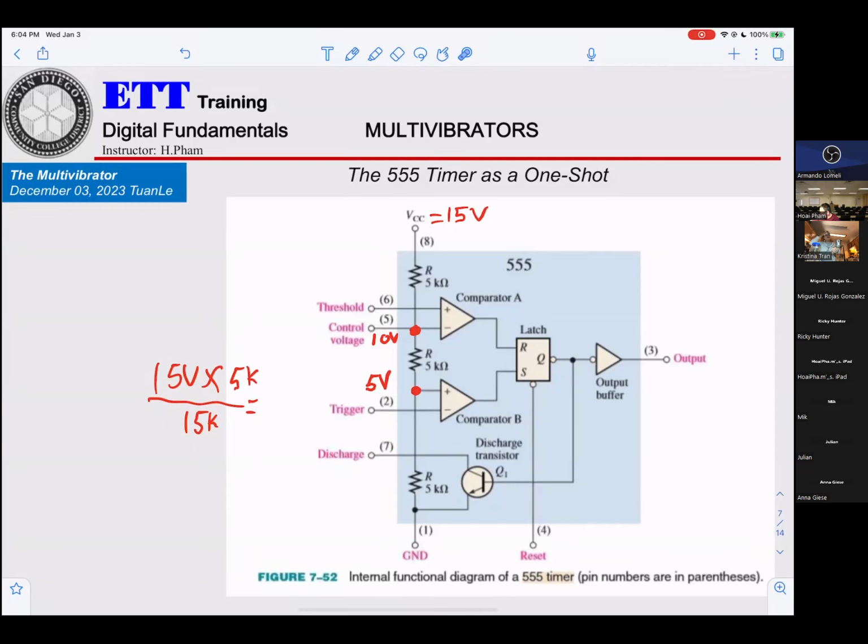So if you connect a capacitor here, that means when Q1 is on, it will be discharged. The signal goes here, goes to ground.